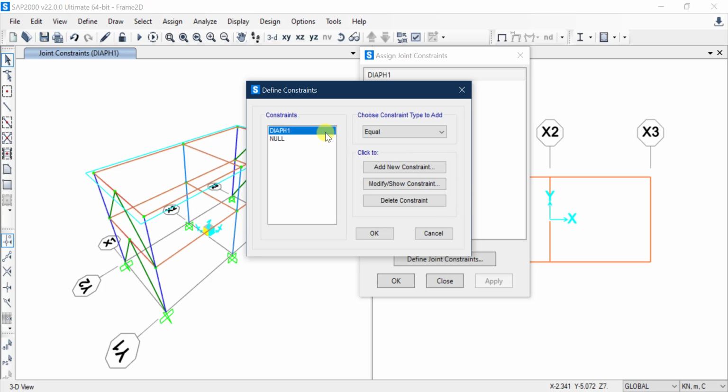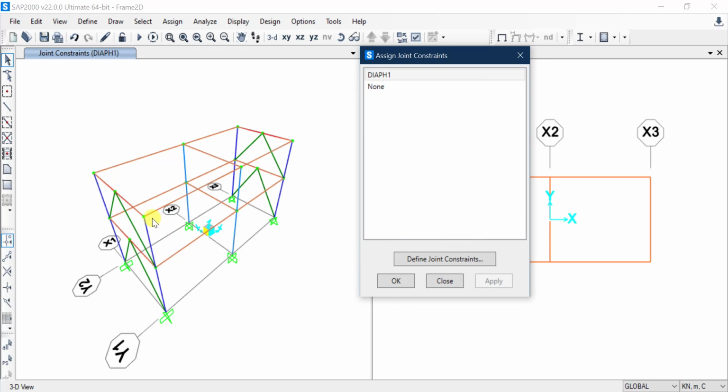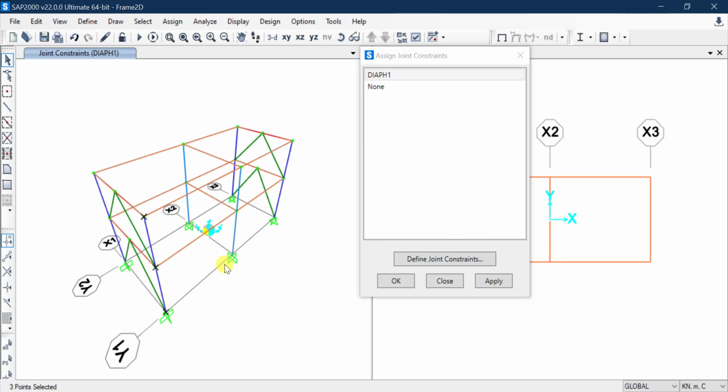So the diaphragm is not only important for floor movement, but also if you have some kind of concrete wall, like a structural wall in one panel. In this case, you will need to select, let's say, the points around this wall and assign them some kind of diaphragm to say that they are moving in this plane, they are moving together as they are rigidly connected.